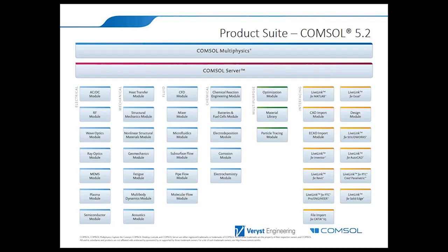Okay, so for our next question, can the custom material model developed for the bone screw be used with any type of multiphysics problem in COMSOL? Yes, they can. Now, with this external material functionality, you can use the PolyMod or any other library in any COMSOL model. And we've, of course, tested it for structural problems, but also for FSI and other coupled problems.